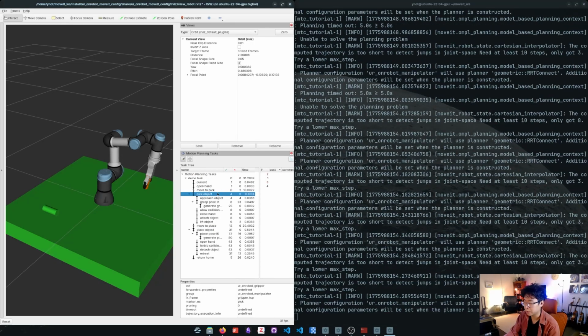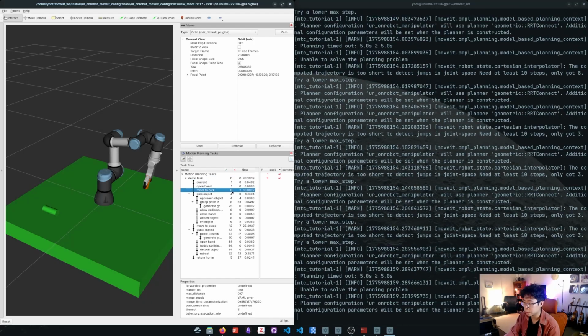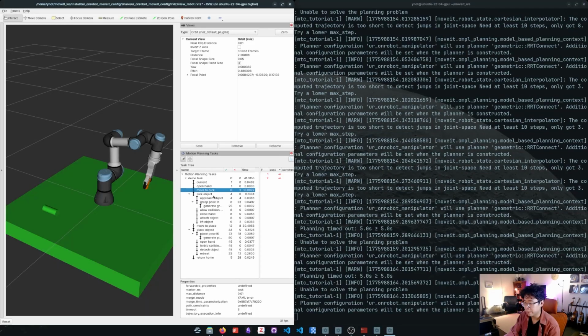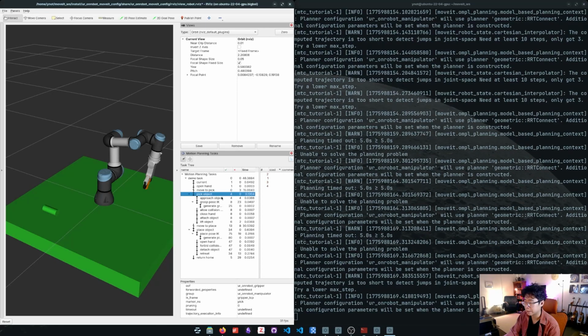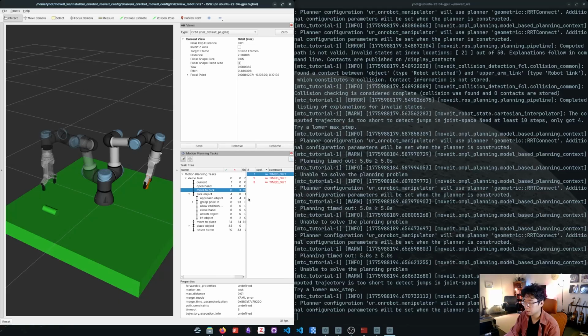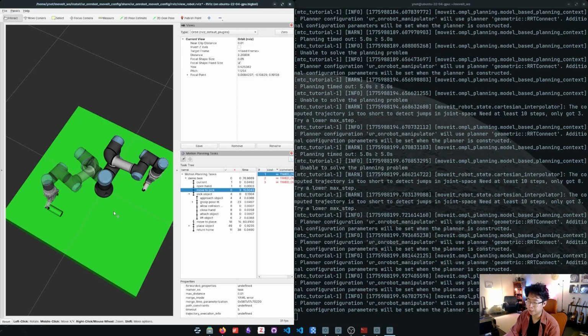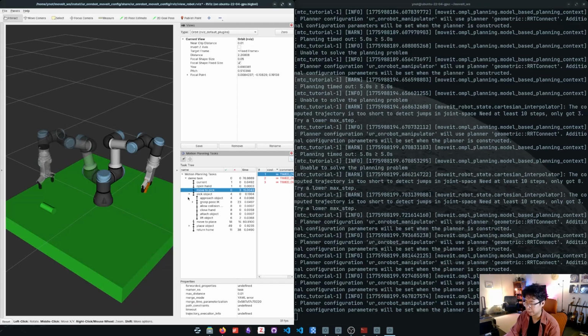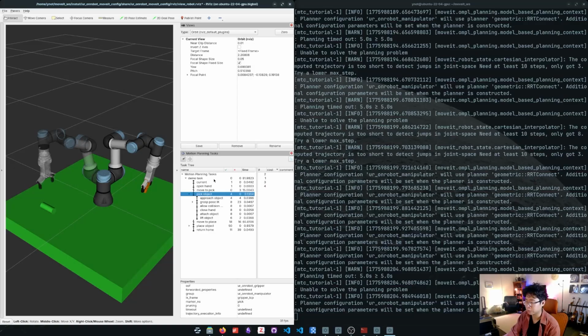It's problematic that all the move to pick ones are failing. This is the one that's problematic at the moment. So whatever solutions these pick objects ones are producing, the bot cannot move to them. And the commands are all timed out. So it might just be such a big motion from here to here that the sampling planners it's using fail to get this very simple move to pick motion.